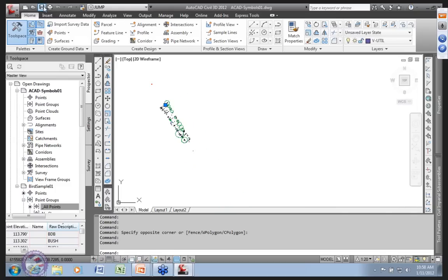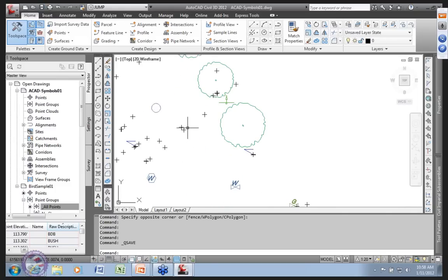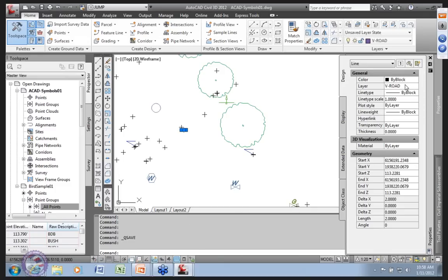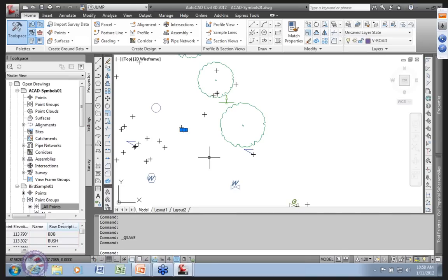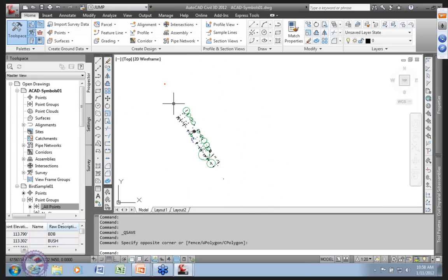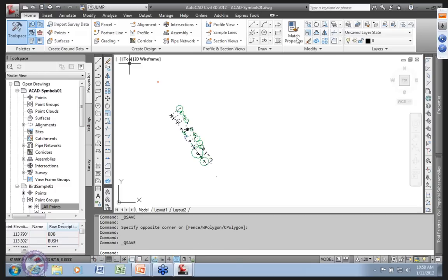Okay, and we're going to save our little symbols drawing since we just want them slapped down. And notice that our little symbols here also went to 0, right? Stayed on the same layer, but become just 2 lines, right? At Z elevation, and that may not be what your customer expects. So that stuff is coming from where? From the point style. Okay, so let's save this symbols drawing and close it.